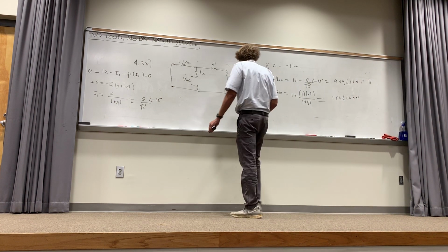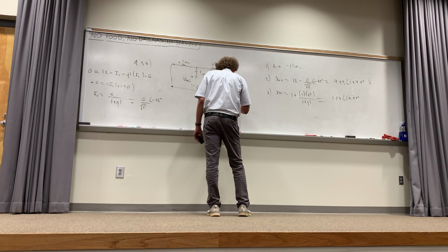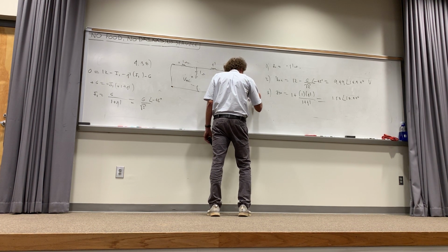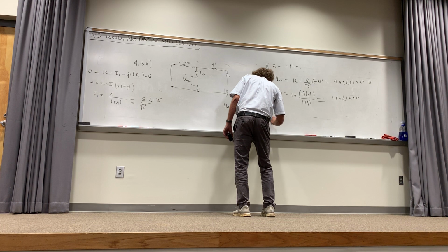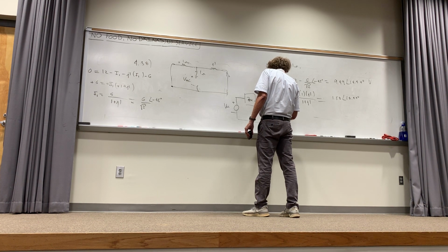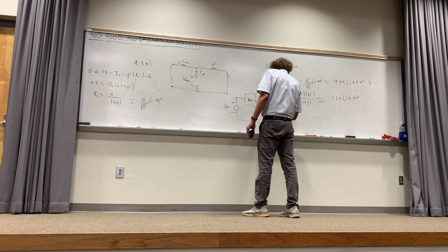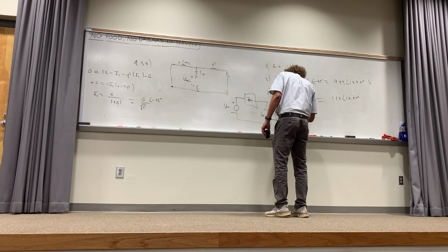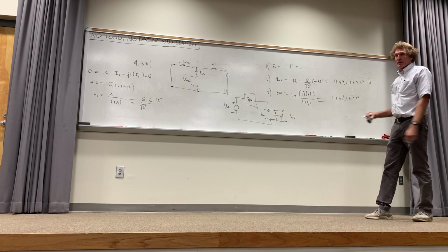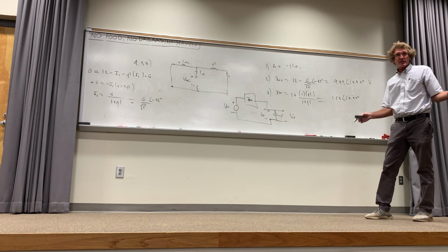Finally, I build my Thevenin equivalent circuit. And I stick the open circuit voltage here. Then I put my Z Thevenin here, right? Those are the terminals where I can put anything I want. Specifically, I'm going to put the load here, and that's minus J1. And I want the voltage right here, V out. So V out right there, y'all agree we have V open circuit, right? Y'all agree we have Z Thevenin, correct?